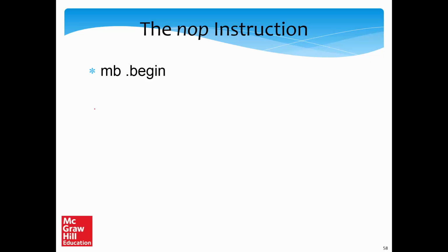The NOP instruction, well, this cannot be simpler. You'll be really happy to see the code. We do nothing at all. We just jump to the beginning of the preamble and we're all set to load the next SimpleRisc instruction. We just jump to the beginning, mb.begin.